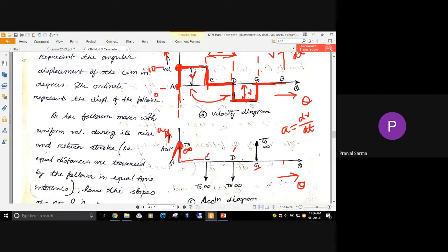So after that there is nothing, no acceleration, so throughout it is a similar case. Now once again if you look at C, this portion, here it was having some velocity, and all of a sudden at the C point itself the dwell has started, and velocity goes from 10 to 0 within no time. That means deceleration, in the opposite direction, that is also infinite deceleration, retardation. So at this point we are showing it with an opposite direction line to infinity, deceleration to infinity. Now the dwell is over, so no problem.